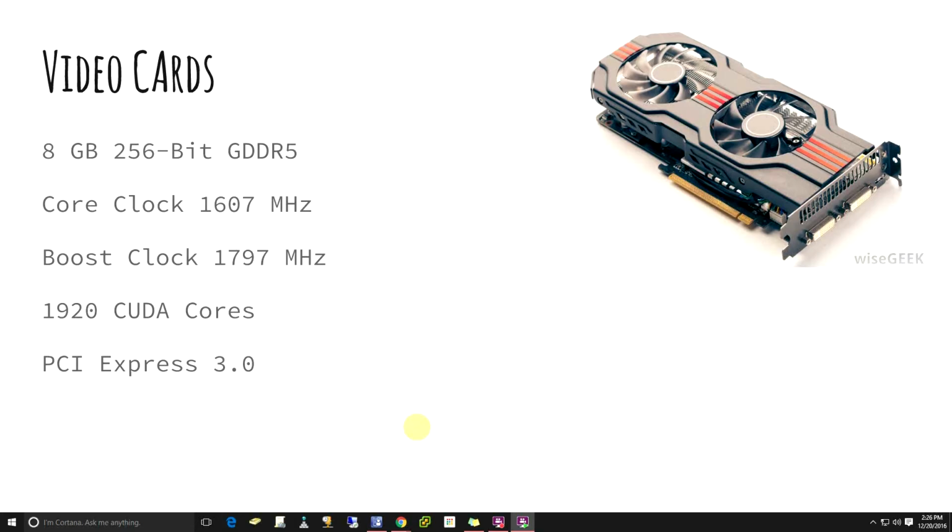One of the other big things we're going to look at real quick is memory bandwidth. The bus width, which we've talked about in multiple videos now, or the amount of data the video card can actually access from the memory each clock cycle, is the memory bandwidth. The more you are doing with the video card, the more bus bandwidth you're going to need. This is basically where you have your bit rate. Up at the top you see the 8 gigabytes, 256 bit. 256 bit is one of the nicest you can get out there, and allows for a lot of transfer of data.